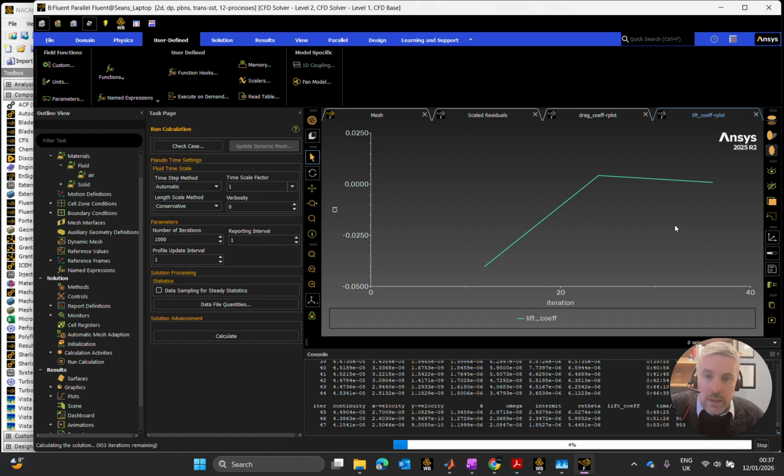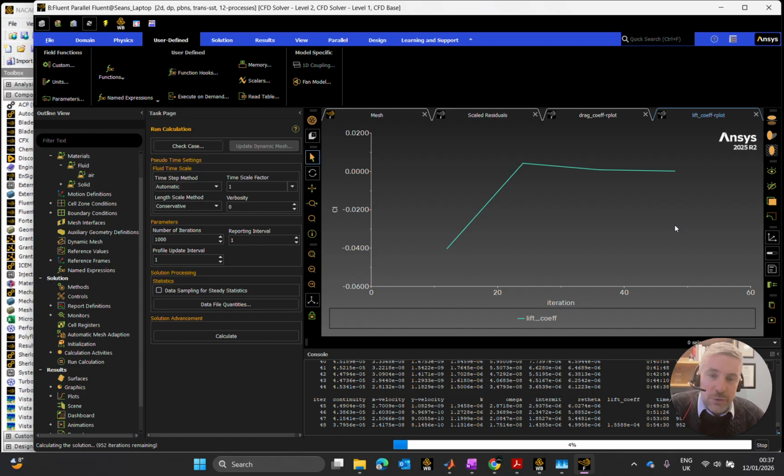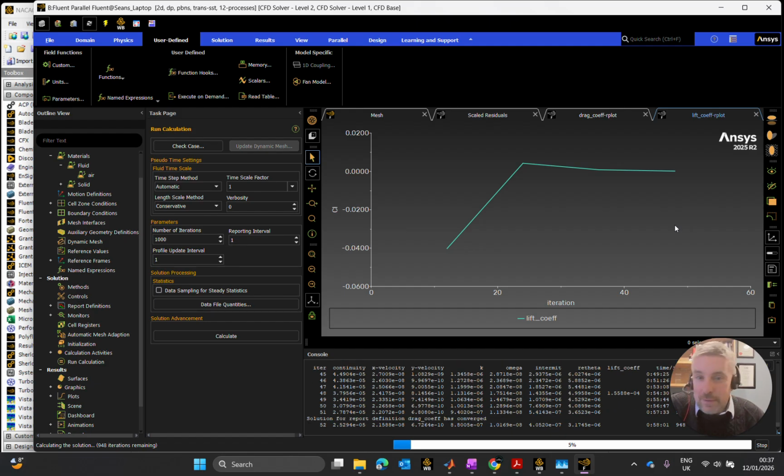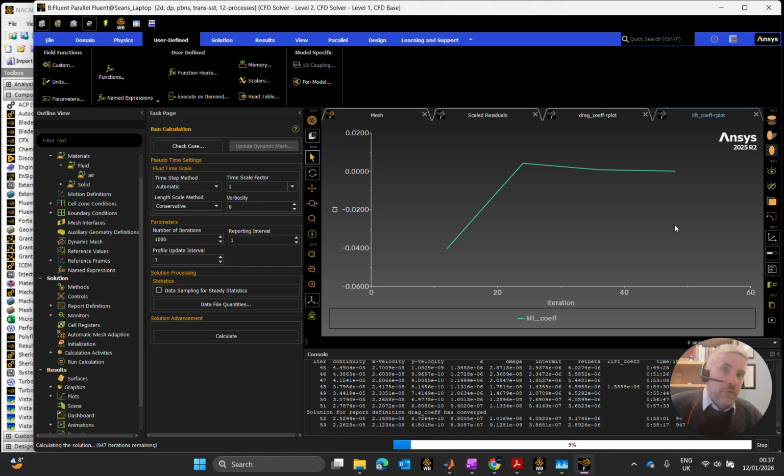So if you are using a NACA 0012 airfoil as part of your STEM racing solution, whether it be on a front wing or a rear wing or winglets or anything like that, just be careful of Reynolds numbers of 50,000 and its behavior. That 12% chord thickness is something you're looking at.